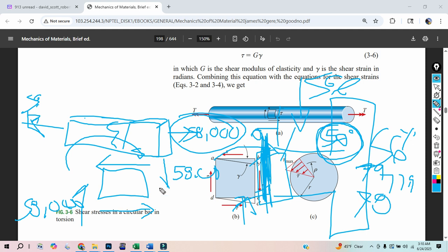But when we put this downward and upward, we have a distance here, and it creates this moment. We got to balance it. So look at this. We're applying 58,000 pounds. And that's where I just think this is a really good thing to go over, because the textbooks, they just go right to this picture with a tau, and no one likes tau, and it's all confusing as hell.